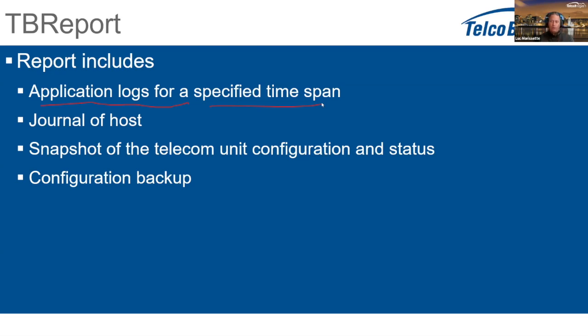For a new user, it can be very difficult to find where the errors are, but for our support team, we know where to look. There's also one specific application called TBSys logs, and this puts all the errors that it sees in all the applications. So one good thing is to start with that TBSys log application. You can see if there were specific errors, and usually if you see an error there, you can concentrate on that and fix that first.